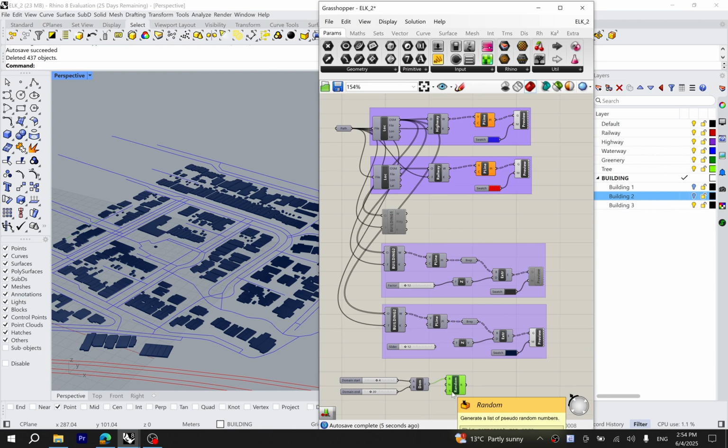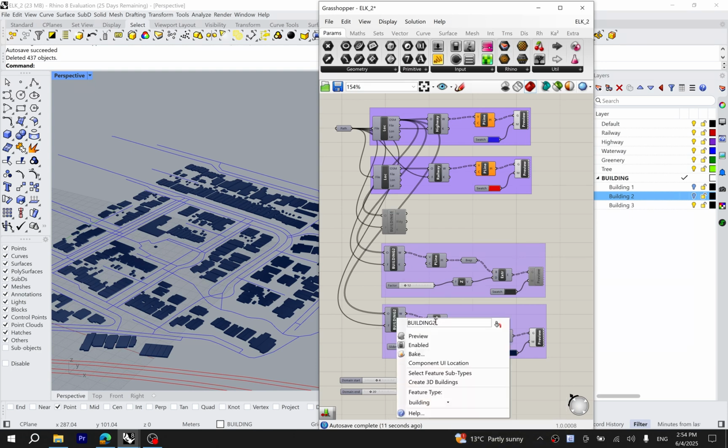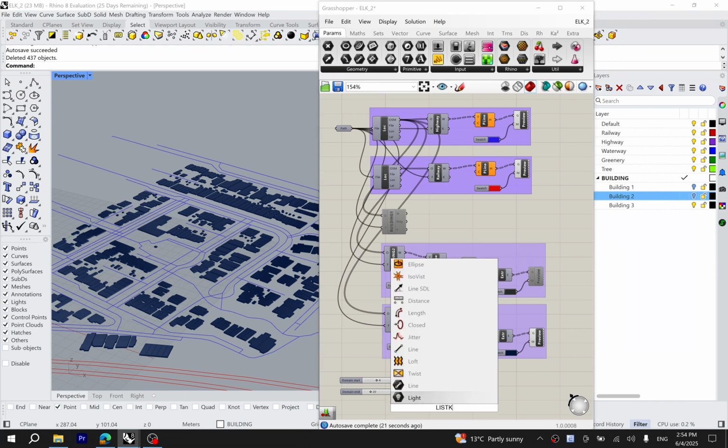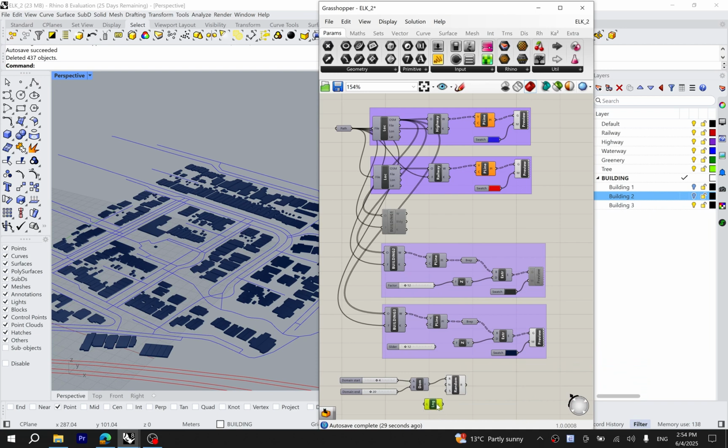Now the same with seed. It is the random engine that we would take from OpenStreetMap data, and to translate it into a seed input we will use List Length. Type list length. Then connect the OpenStreetMap data to list length and connect it to seed. This allows us to translate the data into numbers. Then I connect the random component to the Z direction of extrusion.